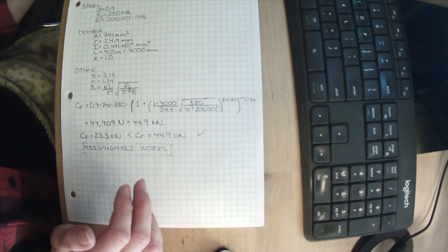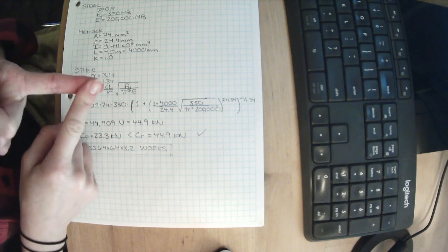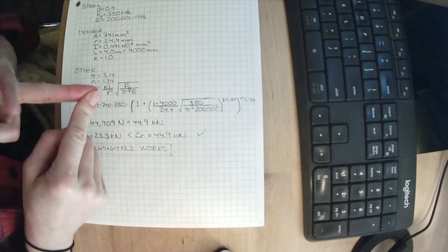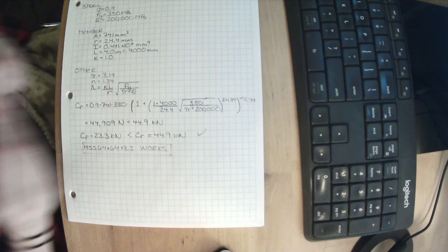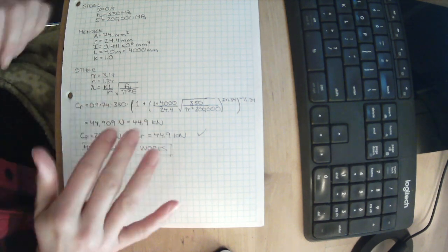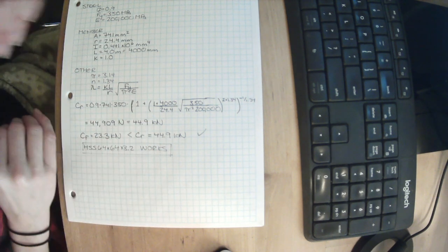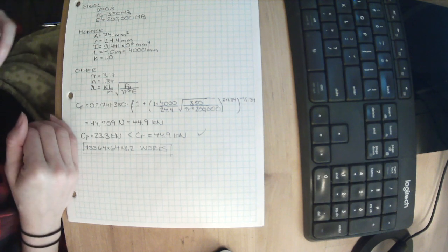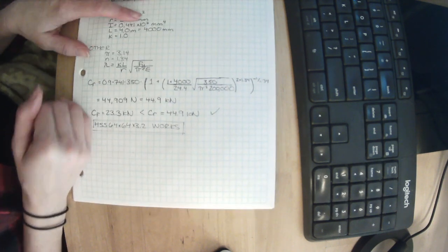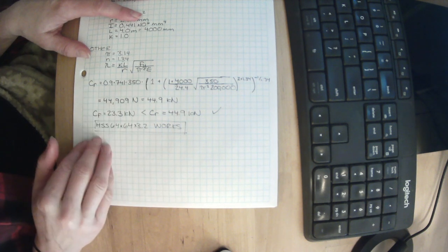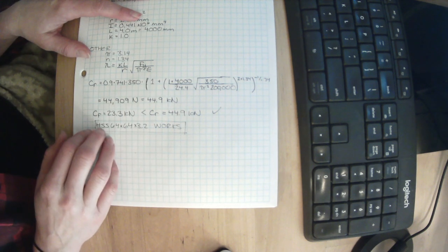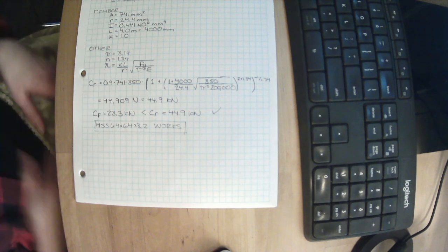The sizing guideline doesn't look at that. It doesn't look at tributary area and it doesn't look at the load. It just looks at the height. So you can see that those sizing guidelines aren't that effective, except that they can be very, very helpful. What they didn't do is tell us that we could use a much smaller column. So that's a very helpful thing.